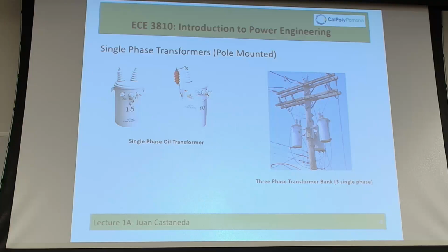And basically, for these transformers, the single-phase oil transformers, the main cooling on the ones that you see up on the poles is the oil. But obviously, having metal helps because you use the metal as a heat dissipator, right? The idea is that the oil goes to the wall, and there's ambient air, just the breeze, and it's cooling it, right?